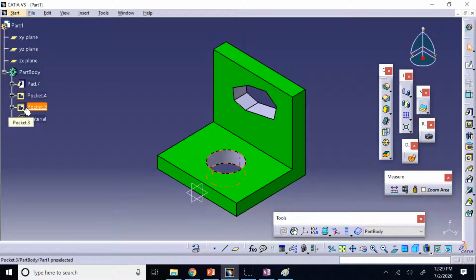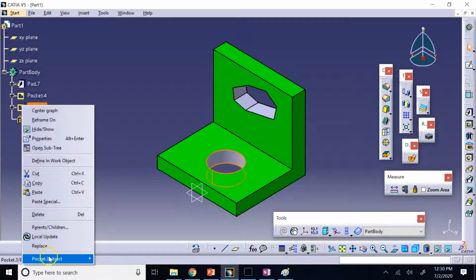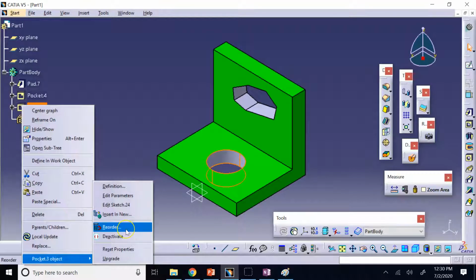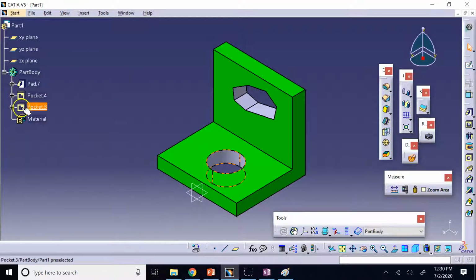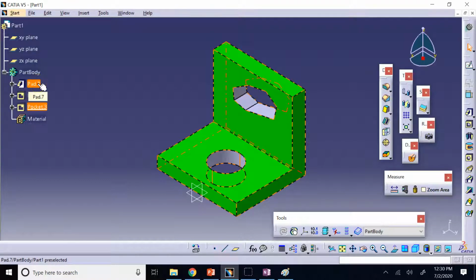the method to get around it is you right click on that sketch, go to the sketch name, and then say what? Reorder. By reordering, you can bring that sketch up to before your loft. When you bring it before your loft, it is as if you created it beforehand. So now that loft can use the sketch.